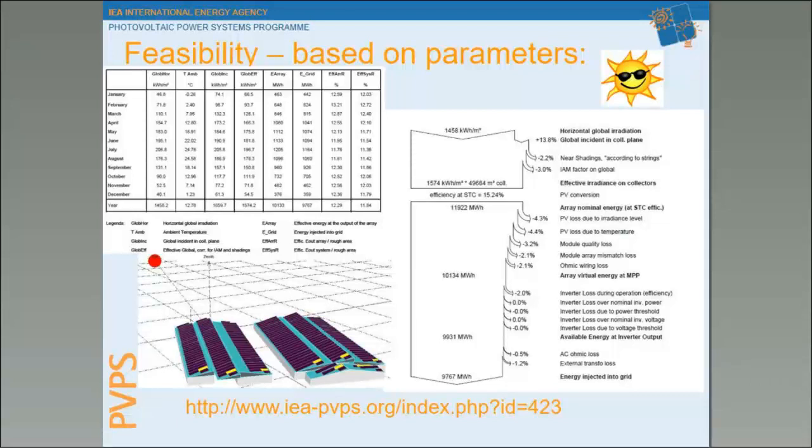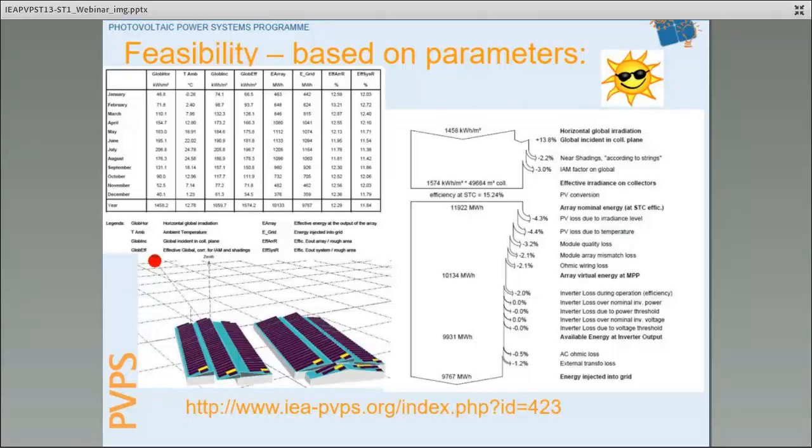4 users came up with results spanning values with a 15% spread. This is due primarily to the choices made by the operator when choosing the simulation characteristics to be used by the program. We therefore suggest that the development team runs simulations using different operators, and that the operators then discuss between themselves the choices made that are responsible for any difference in results, and then analyze the actual level of variance that should be used with the solar resource parameter in calculating the financial output for the project.